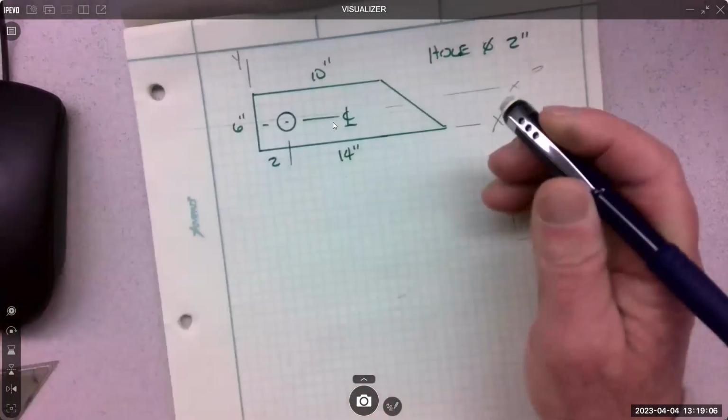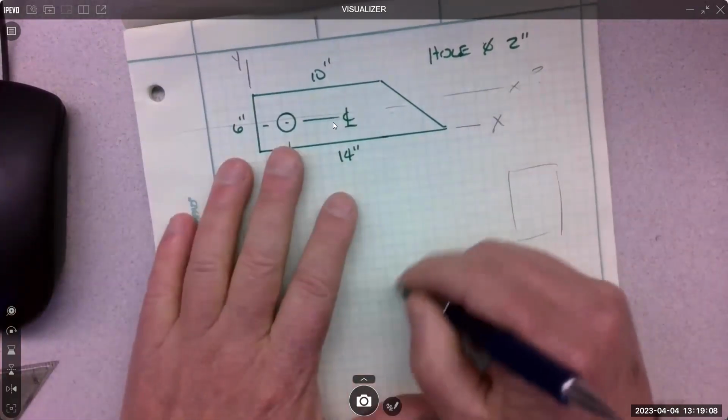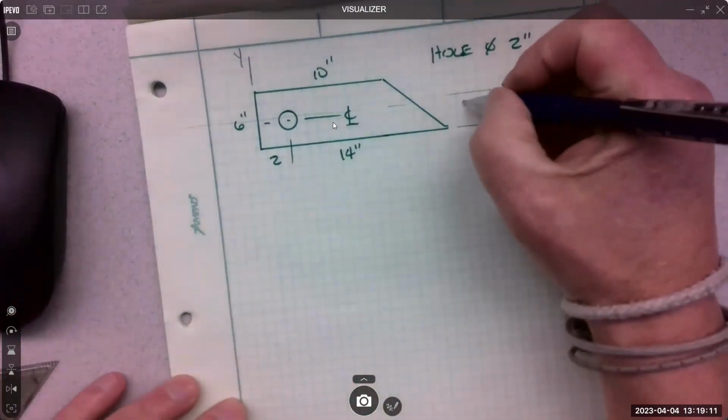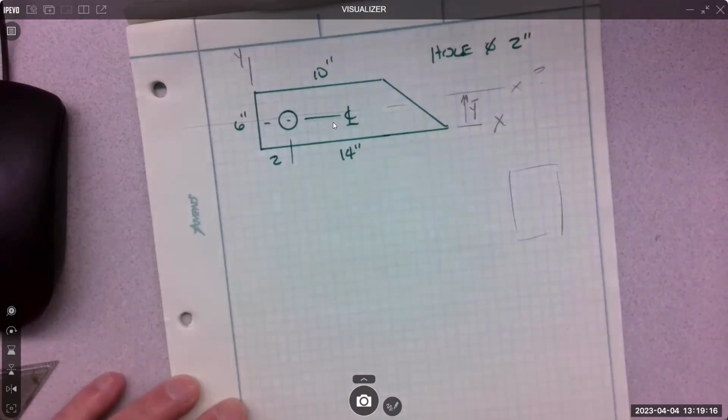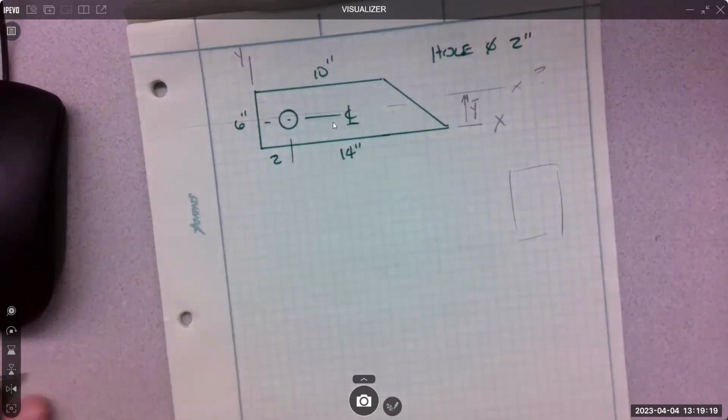Look at that. Clean slate. Anyone remember the formula? So remember that Y bar locates the x-axis. That's the first confusing thing: Y bar locates the x-axis, X bar locates the y-axis. And most of the time we just need the x. If we just have one loading condition coming straight down, we need the x. If there was a side load, some kind of seismic load maybe, then we'd need to know the location of the y-axis.